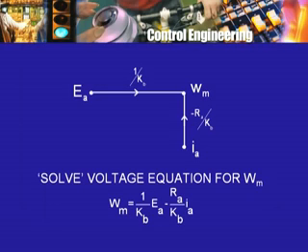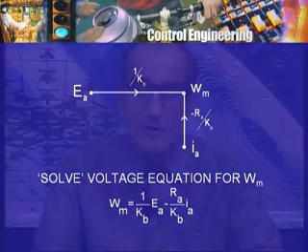So this represents the EMF equation, and we have solved the EMF equation, or rather we have rewritten it. The signal flow graph drawn so far represents that equation in a different form. Omega m is a sum of two terms. There are two signals coming towards omega m. So omega m is 1 by KB into EA minus RA by KB into IA. Just check that this is correct. Now we look at the second equation.